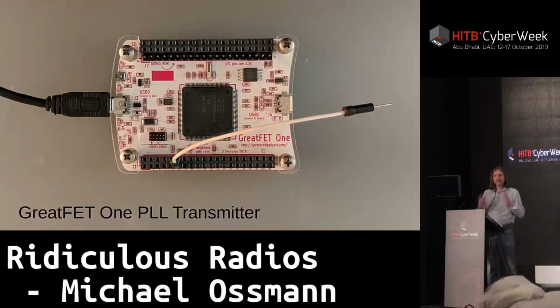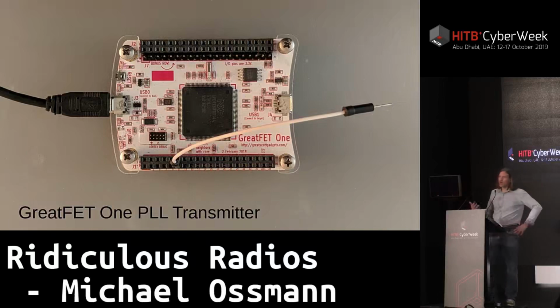So instead of having the data encoded in how the signal turns on and off, this has the data encoded in how the signal changes frequency over time. The signal wiggles between two frequencies, and when it's the high frequency, it represents a digital 1, and when it's a lower frequency, it represents a digital 0. So if you plot how its frequency changes over time, you'll see it's high and then low, and then high, low. It's on the whole time. The amplitude doesn't change, but the frequency is modulated, and that carries digital information.